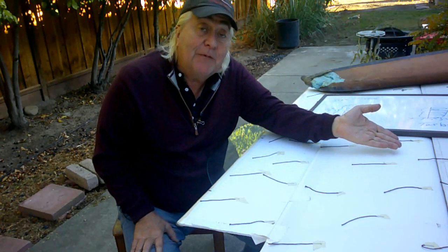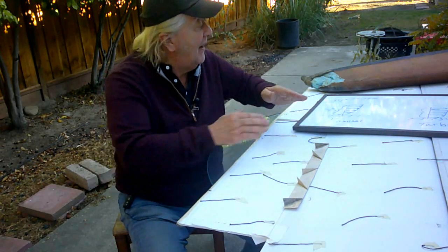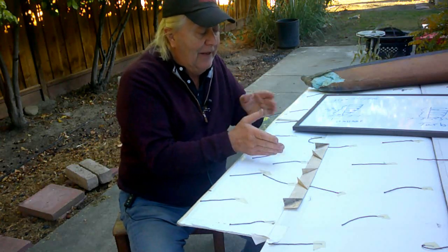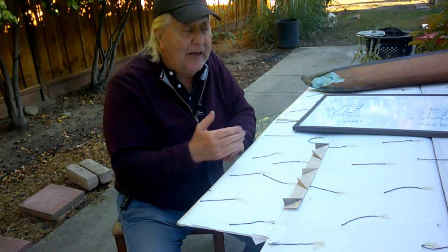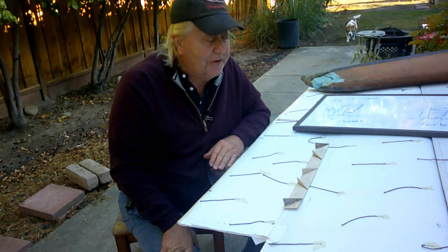Now, those vortex generators are not optimum. They're well off of optimum. And if I had them full length in front of the control surface, and they were spaced properly, right height, right angles, maybe they'd work considerably better, and I'd get another degree of deflection or so.